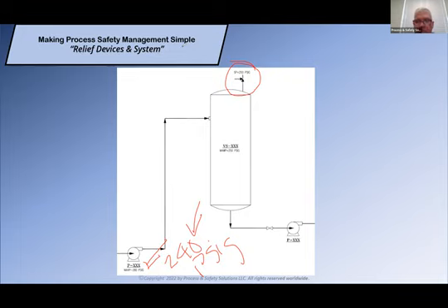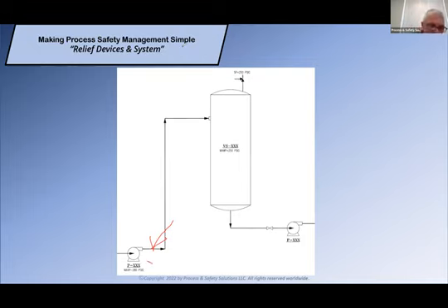If I didn't document that, then at some point, just like in most processes, somebody comes along and says, hey, I need more production, so I'm going to increase the impeller size in this pump, or I'm going to replace that pump with something that gives me 280 PSIG and more flow. If this relief valve is still only sized for the vapor case, then because I didn't document that information originally, I couldn't go back and see whether that would now be a scenario I have to address. In most cases, it gets forgotten.